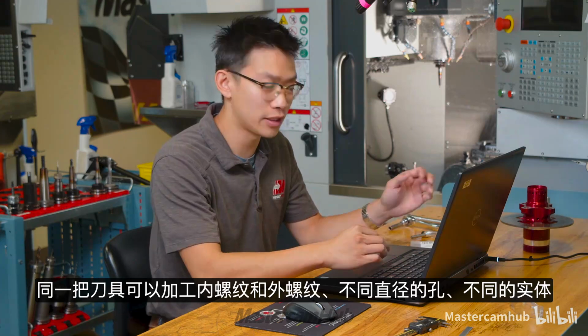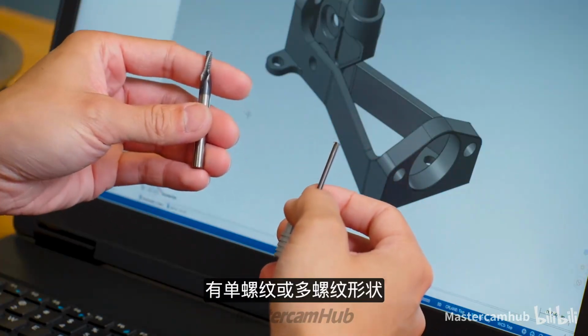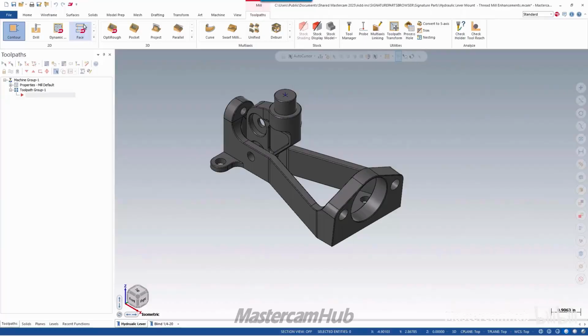Thread mills are versatile in which the same tool can be used on both external threads, internal threads, and multiple diameter holes and body sizes. Thread mills come in a variety of different sizes and pitches with a single or multiple thread profile. Let's create a thread mill operation on an ID feature.